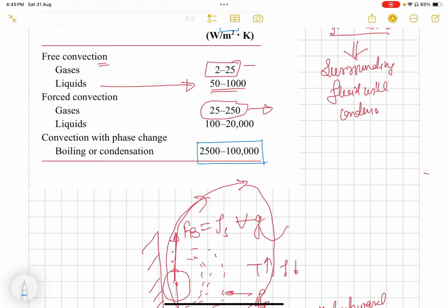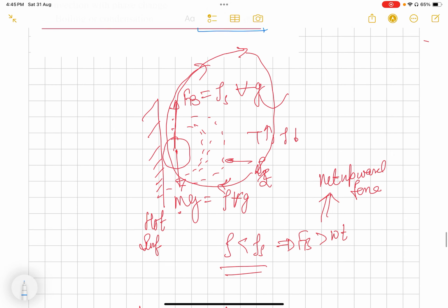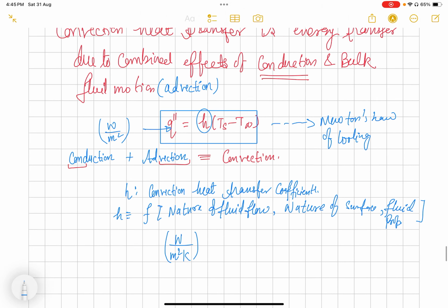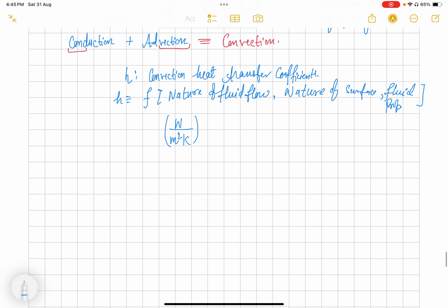Again that fluid comes back to the CPU location, takes the heat from the CPU and goes back to the other location where the vent is, and it transfers the heat to the surroundings. So that's how heat pipes are used in laptops to cool, and they employ this phase change convection heat transfer process.